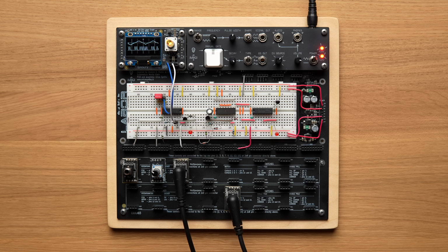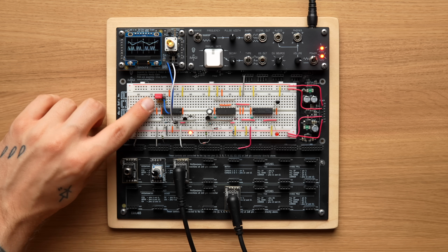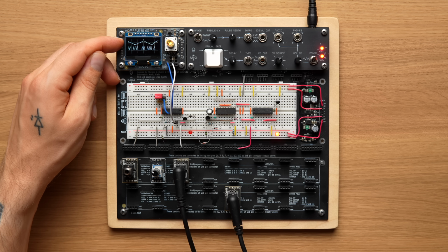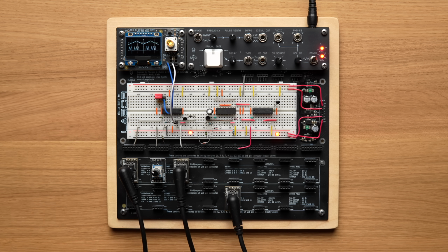Here's how this works out in practice. I've connected my scope to the integrator's output. As expected, we get a slow triangle wave. Next, I'll patch it to the drum module's accent input. That's not what we expected. Instead of just going quiet, the hi-hat cuts out completely for part of the cycle.